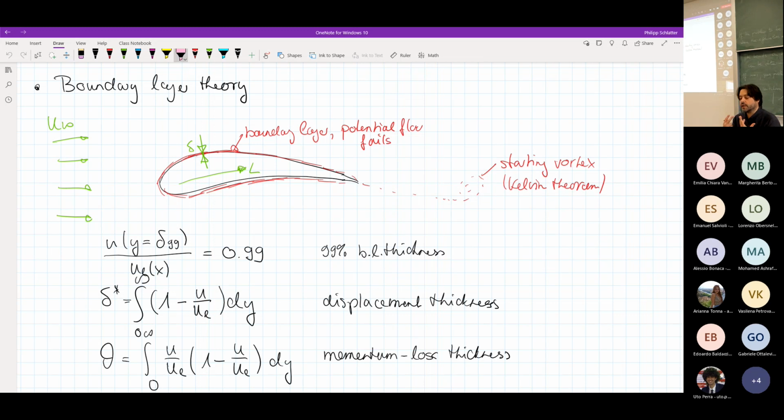So all the sharp changes of the velocity that are due to viscosity are happening in this thin boundary layer. That means in this region you need to do a viscous solution, so it's not potential flow, it's not Euler that you can use, but the good thing is it's really only confined to a very thin region. And I guess the main aspect with boundary layers is that the thickness of the boundary layer is much, much smaller than the length of a body in such a domain. So that means that delta over L would be much, much smaller than 1.